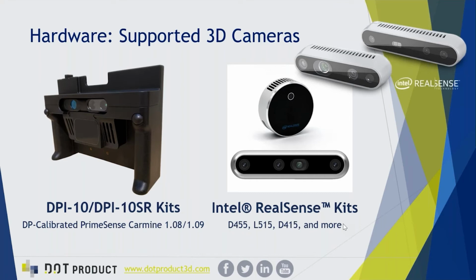And then we also have on the top right here a couple more of the D400 series of Realsense cameras, which we do fully support. So if you have a D415 or a D435, those are supported, although not normally recommended now that these new cameras have come out. The one benefit of the D415 over the D455 is that it offers some excellent colors even in bright sunlight. There's sometimes a bit of tinting with the D455 in bright sunlight, although they both work very well in that situation. So 400 series are your outdoor capable options.